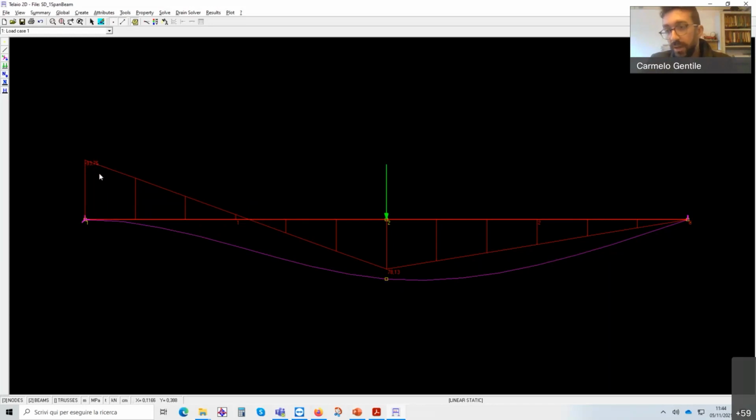We usually draw the bending moment on the side where we have tensile forces. So in this case, it is positive mainly in the span of the beam. In fact, in the midspan, the bending moment is obviously positive. And that's why we have a positive bending moment of plus 78.13. This positive bending moment is everywhere we have an upward curvature.